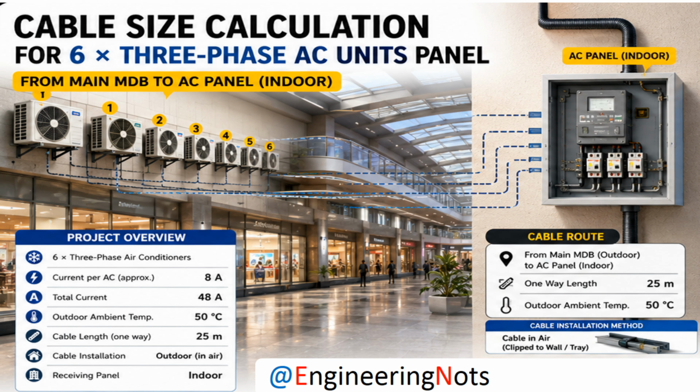First, because the cable run is relatively short, we can start with the current carrying capacity, or ampacity tables, rather than making voltage drop the main sizing factor. Now, we have 6 air conditioners, and each one draws 8 amps. So, 6 times 8 gives us 48 amps. Therefore, our starting load current is 48 amps.